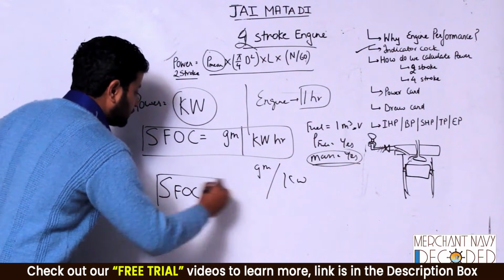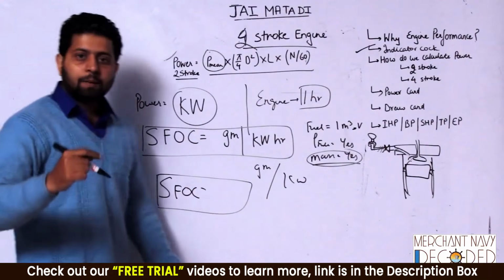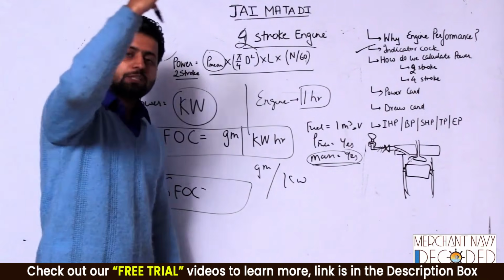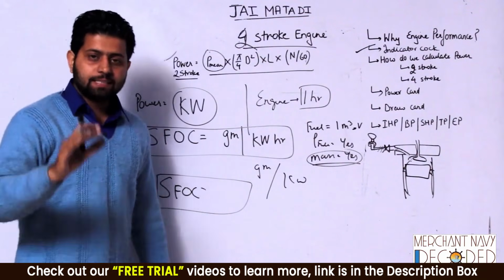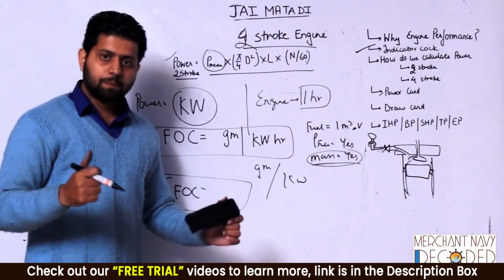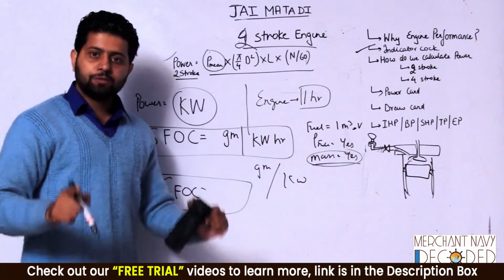And this SFOC, when we calculate and compare it with previous readings and with the readings when our engine was new, that is how we get a very good idea of how our engine is performing. Copied, guys? Now this was very important for you to remember.